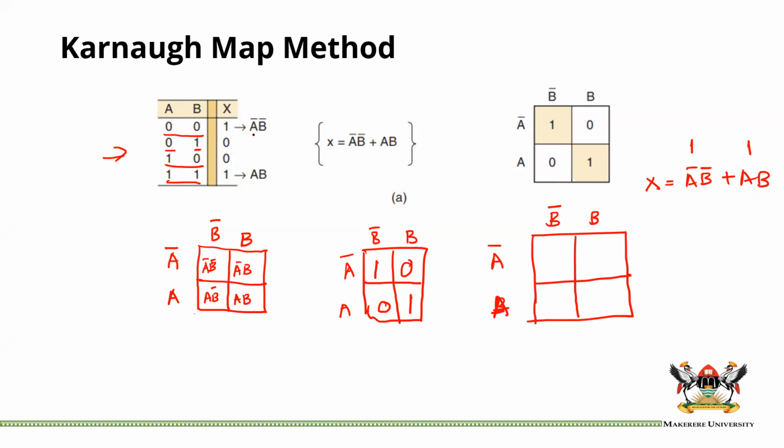So you remember, you have your K-map, you get these products. If I have A inverse, B inverse, I know that is the box for A inverse, B inverse. I know that is the box for A and B. And then I know that the rest is simply 0. This is a two-term circuit, a two-input circuit, and the truth table always looks like this.